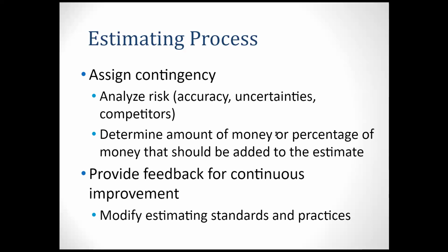All the things we mentioned earlier are based on the quantity takeoff, and based on your history data, you get a price, right? And then we're adding some new things here. That sense of not being certain is the contingency. Maybe we have some risk over here. So the risk can be the accuracy, the uncertainty, and the competitors. Competitors is easy to understand. You're not the only contractor going to get this project, right? They may have some competitors over there because this is a competitive bid, right?